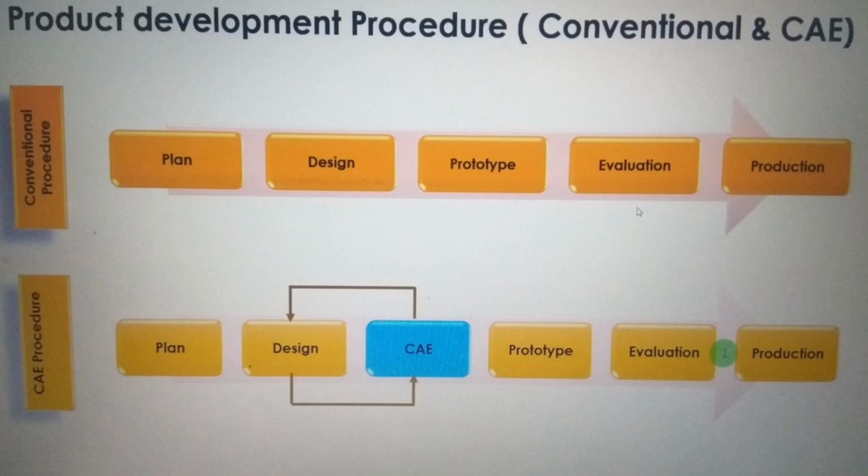One drawback with the plastic material, what they saw is, when the bulb was emitting constant light, it started generating heat. So because of that heat, the plastic began to deform. So this was again a failure. So after that, what they did, they increased the thickness of the plastic and they tried to design a different type of plastic with some designs on it, with some floral patterns on it, like natural stiffness, something like that. And they found the CAE results were much better than the initial plastic bottle. So then they went into the prototype.